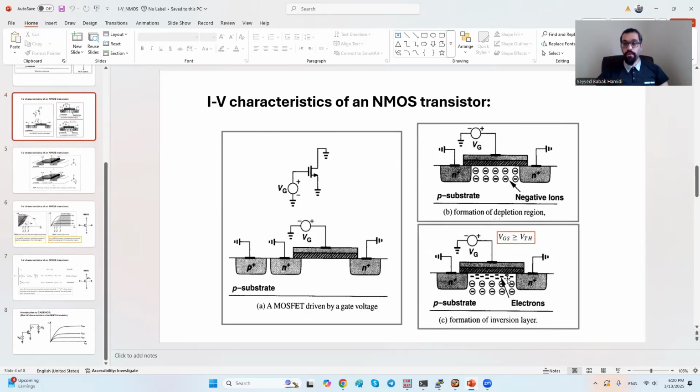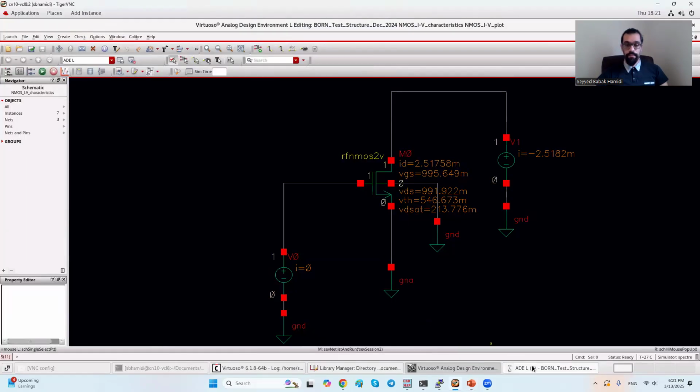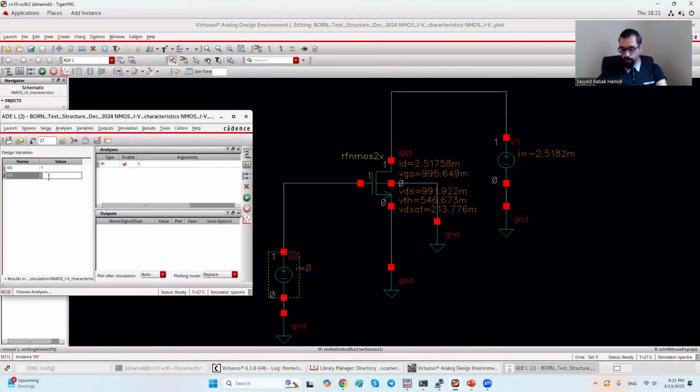We know theoretically that there would be no electrons, and even if we put the voltage on the gate and drain, because you don't have that channel, no electron mobility, you would not see any DC current. So let's put the VG less than that 0.5 volt. Let's put it, for example, 0.2. VG as 0.2. Still, you have a voltage on the drain. Let's simulate.